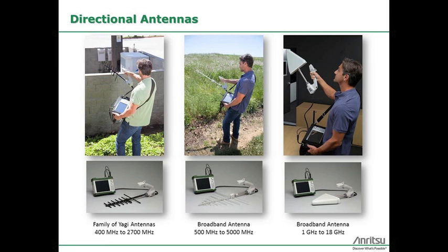With the various directional antennas that can be attached to the instrument, you have some easy tools for getting the exact coverage you need over the frequency range you need. And if you're doing something really broad, you can choose some of the log periodic antennas. If you're doing narrower things, channelized work, you can choose the higher gain Yagi antennas.